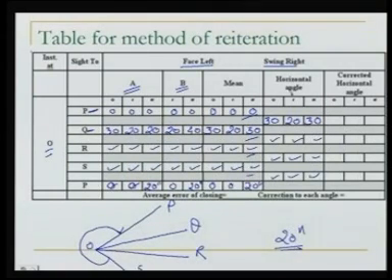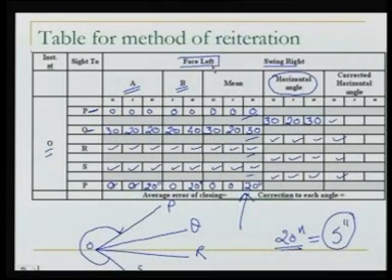Now so far in these horizontal angles, the correction has not been applied for the misclosure. What we can do, we can apply the correction for the misclosure, as we found it should be 5 seconds to each of these angles, and we can write these corrected angle values over here. So this is one face left reading.